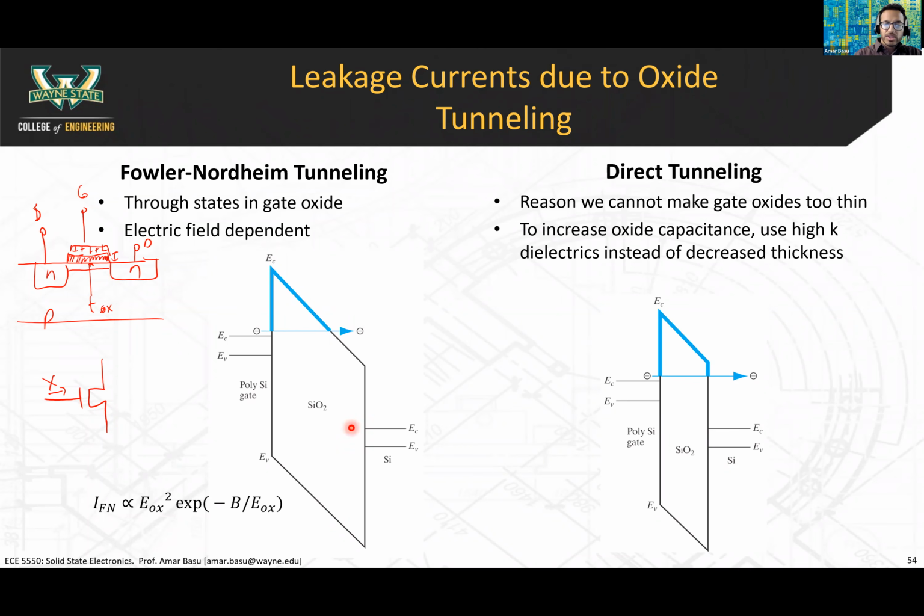So this is showing the MOS cross-section, the MOS energy band diagram for the device. This portion is your metal. Actually, this is a polysilicon gate. That's why it has the EC and EV. Okay, but this is your gate material. You have electrons in the gate. You've applied a potential between the gate and the substrate.